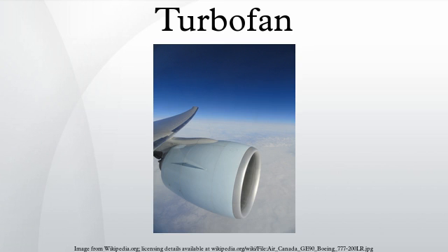For reasons of fuel economy, and also of reduced noise, almost all of today's jet airliners are powered by high bypass turbofans. Although modern combat aircraft tend to use low bypass ratio turbofans, military transport aircraft mainly use high bypass ratio turbofans for fuel efficiency.